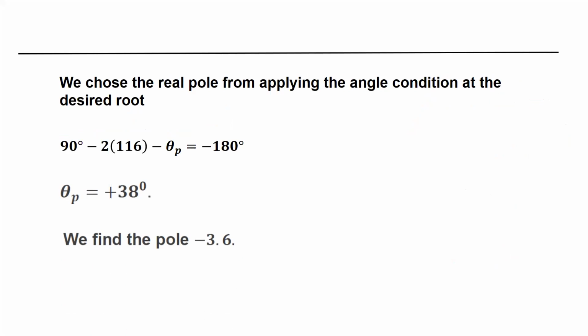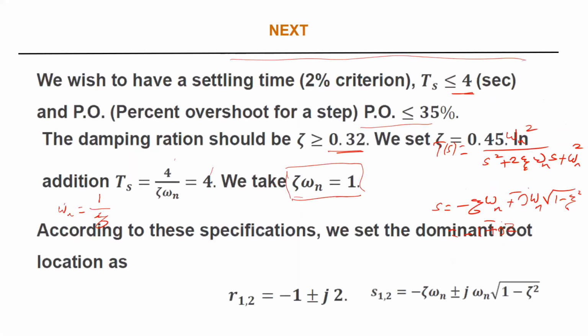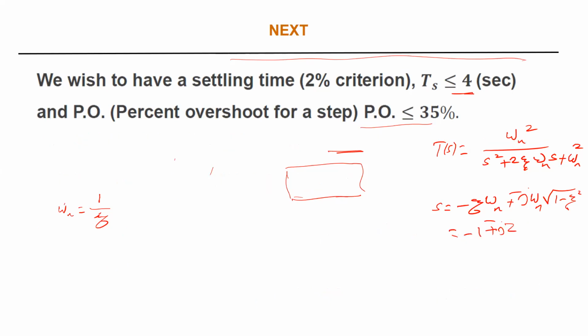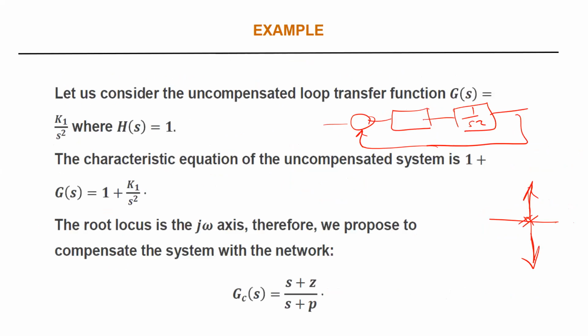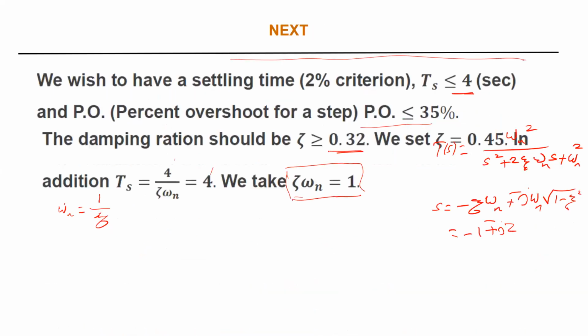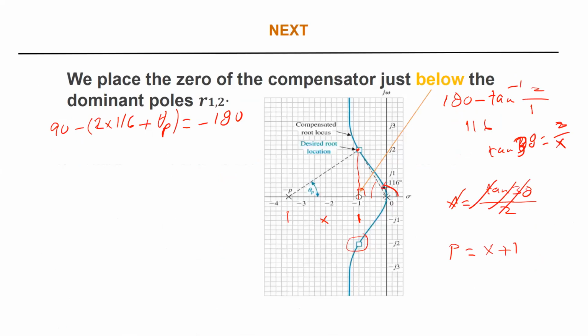Now, what I want to do is calculate, for this system, the steady state error for step input. What is the system type? It's type 0. Wait, no, sorry, type 2. So the steady state error for step is 0, for ramp is 0. If you want to find the steady state error for parabolic, then we need to calculate Ka.